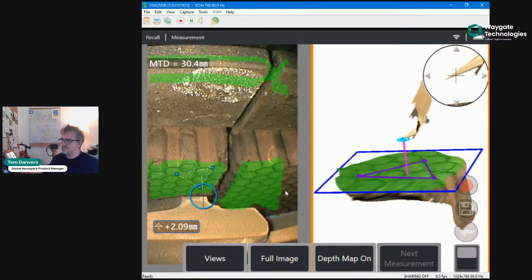If you were to use measurement plane for depth, measurement plane is going to force your 4th cursor to the measurement plane. So if I applied a measurement plane on top of my 3 points, that will turn my measurement into 0. So you've got to be aware that measurement plane sometimes helps you, sometimes it doesn't. In this case, it's not required, because you can tell everything on my honeycomb liner is in agreement because of the green mask.